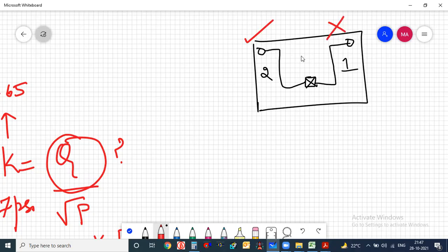So you can just avoid this calculation and follow this calculation. Like that, I think in Gulf countries they are following, or if they are not following also, at least we should go for the 2 calculation sets so that the agencies can approve. Because obviously in any building there are 4 corners. Sometimes if you have not placed sprinklers properly, then in all the 4 places you will not understand which is the hydraulically most demanding calculation. Then in that case, you have to go with 4 sides also. Okay, so it is for our safer side only.